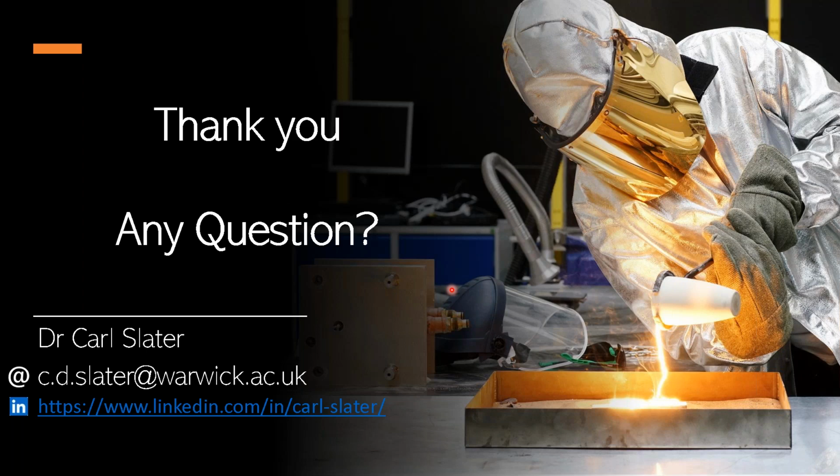Certainly for these ultra high temperatures, I would always use the HDS, because the benefit really is that the bit that's at the temperature that you're going to deform, nothing's touching it while it's heating up. So you could have it at 1400, 1450, even getting closer to 1500, but nothing really is touching it when it's at that temperature. And then you can come in for that brief deformation and then do your cooling.